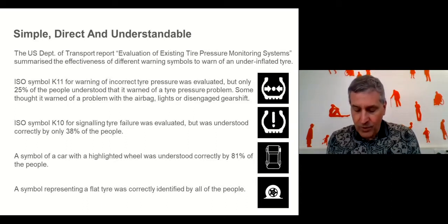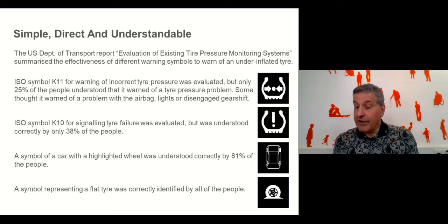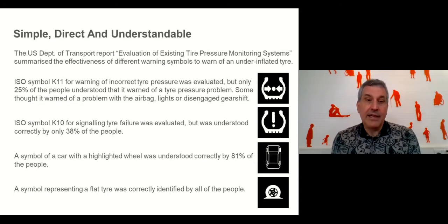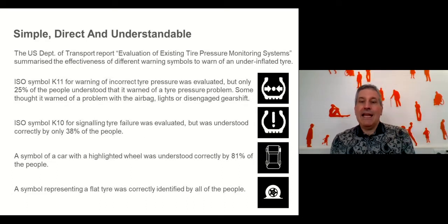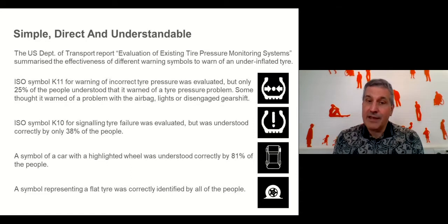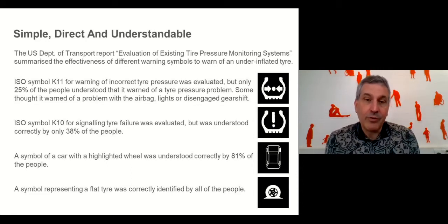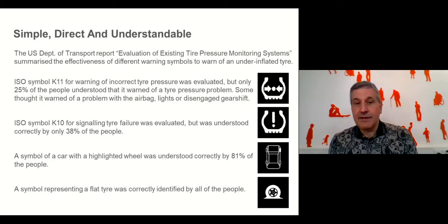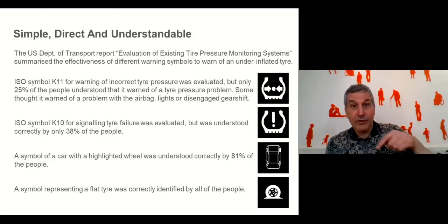So if one of the four tires would lose a bit of air for some reason due to a puncture, a leak, or some other difficulty, the system had sensors in the rim, and it had an air line which went through the center of the hub and could reach the rim, and automatically a compressor would pump some air into the tires, which was a very, very complicated matter because wheels turn.